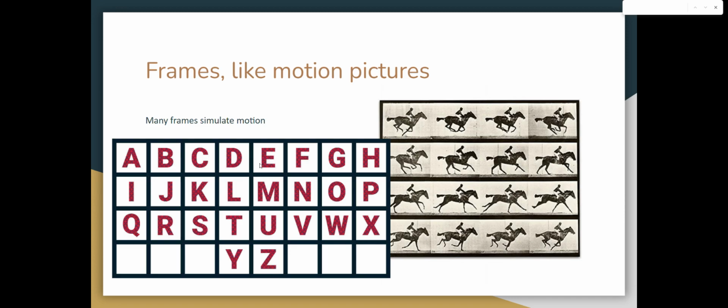What would happen if all of these were missing, and all you got after 1 second is you had A, and then a second later Z? Well, what would happen is there'll be no ramp up. It would go right to full throttle. Boom, instantaneous full throttle. And, you know, that's not really the way you want to fly. It's not really great for the plane. It puts a lot of stress on it. You want to have a nice ramp up.